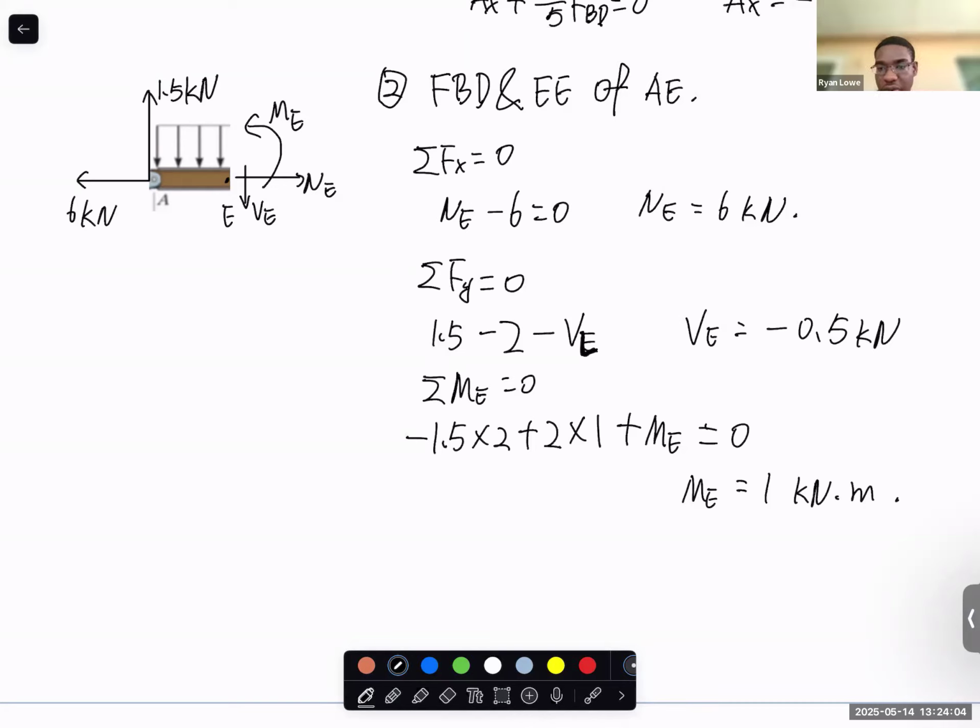It's based on our sign convention of internal force. When we put the sign here for the internal force, we always need to put downward for the shear force as internal force on this cutting surface. But as I said, for writing the equilibrium equation, all the forces should follow the coordinates. It does not depict the global coordinates, but you need to follow the coordinates. So for this one, with the global coordinates, this becomes a downward force when we write the equilibrium equation.